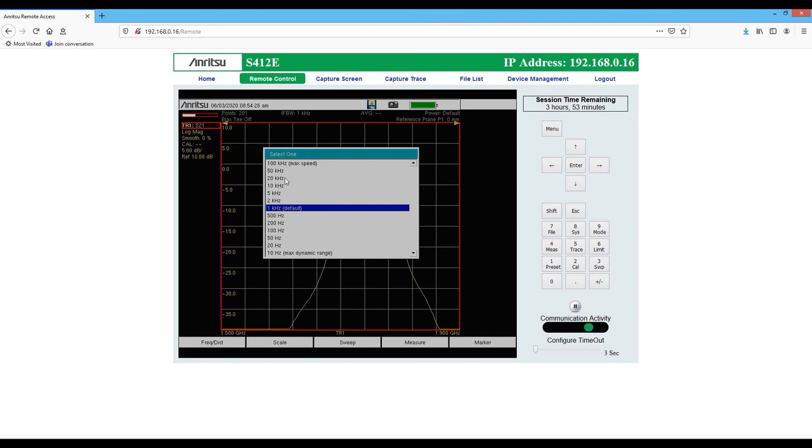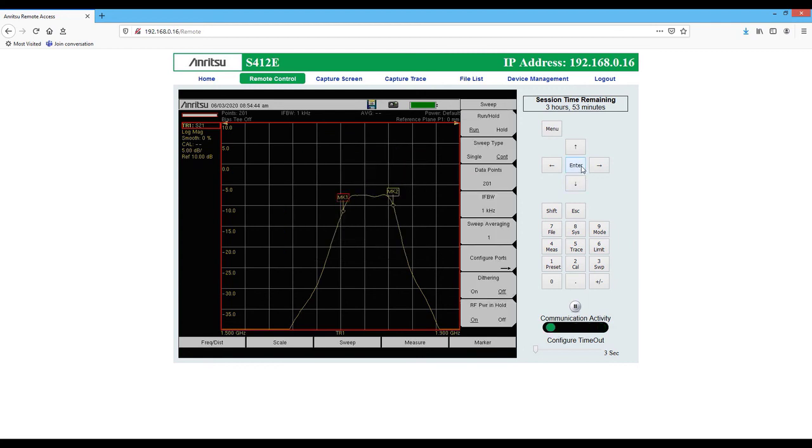And these options are available in this mode. If you go back to field mode, you have 3 options: the 10 hertz, the 1K, and the 10K. Or 100K. We're going to leave it at 1 kilohertz for the default, but that can change the speed significantly because it changes the size of the sweep signal itself.